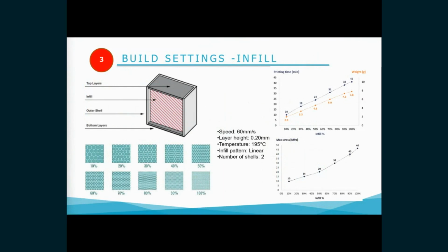Infill density is the fullness within a part. In the slicer, this can usually be defined as a percentage between 0 and 100, with 0% making a component hollow and 100% completely solid. As you can imagine, this greatly impacts a component's weight. The fuller the inside of a part, the heavier it is. The most important of those parameters fall into two fundamental aspects. They are infill density and infill pattern.